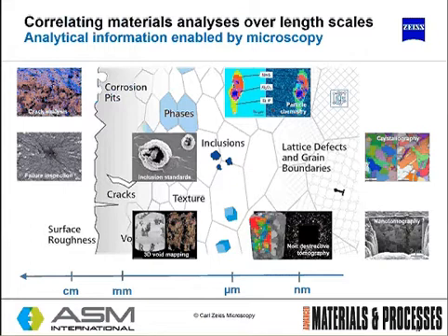Down into the millimeter range, you're able to measure inclusions and 3D voids within both LM and EM as well as XRM, X-ray microscopy. In the submicron range, particle chemistry is a critical application of microscopy in the analysis of inclusions and the chemistry of imperfections. And non-destructive tomography as well, which is an XRM application, and that can be done in the submicron range, which is an additional complementary technique to EBSD, which we'll discuss shortly.